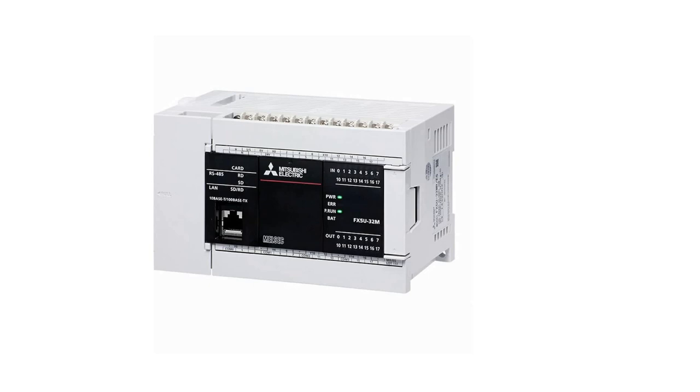As shown in the inputs, there is a numbering 0, 1, 2, 3, 4, 5, 6, 7 and then 10, 11. There is no number 8, 9 because it depends on the bit, that is the digital bit. It works on the binary bit, and we know 8 bits is equal to 1 byte. So according to that, numbering is given from 0 to 7, that is a total of 8 numbers, and from 10 to 17 again a total of 8 numbers.